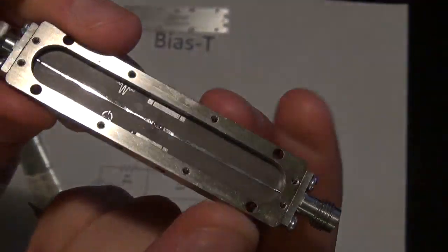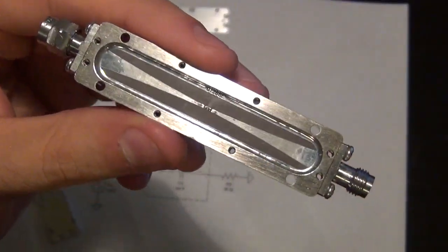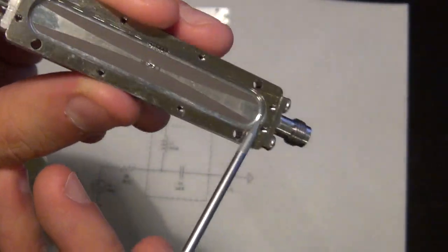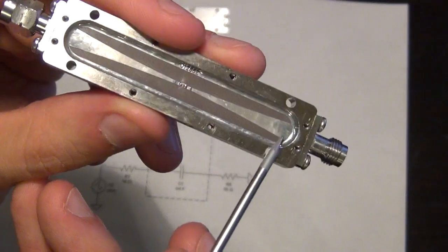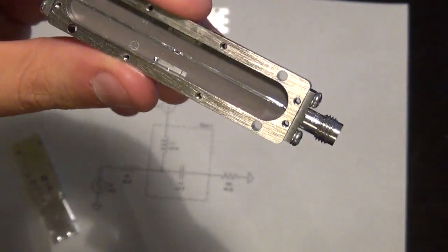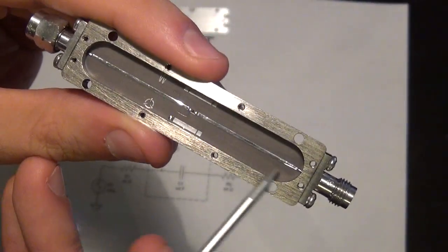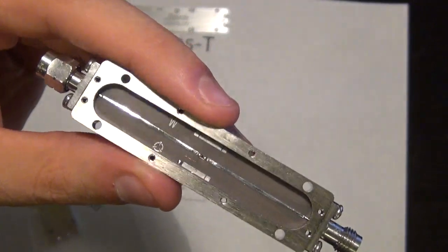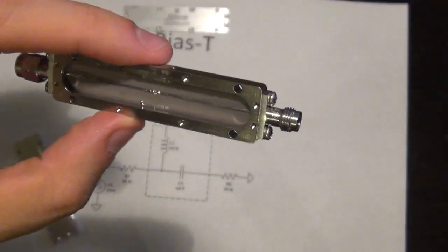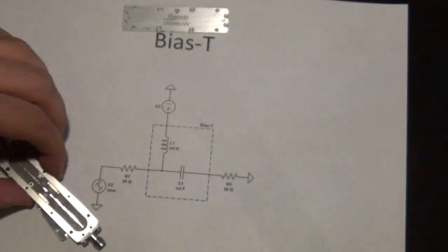The other interesting thing is that this is the path of the signal in and out, and the other side is the ground of the transmission line, and you can see they have tapered the ground. It's a ground line because it's connected to the body. They taper the transmission line ground in order to create a certain varying characteristic impedance to match to the diode, so that this whole thing will be 50 ohm input, 50 ohm output. We'll talk about this type of technique in a different video, but this is a doubler, again, fairly common. People use them all the time.